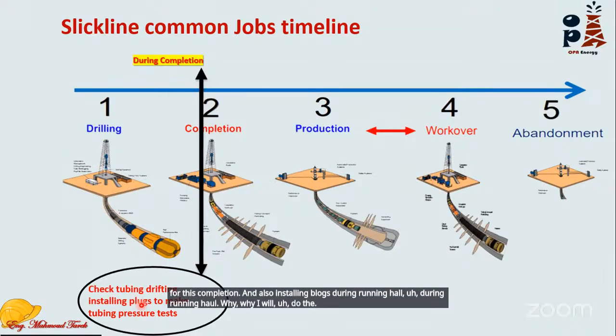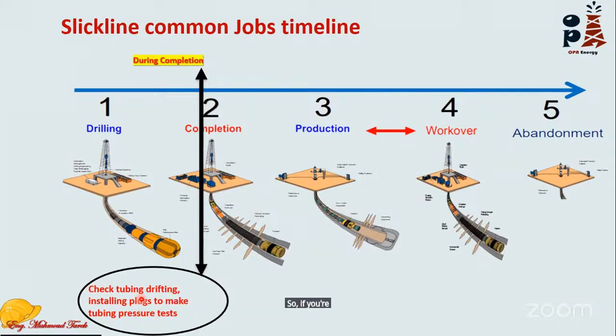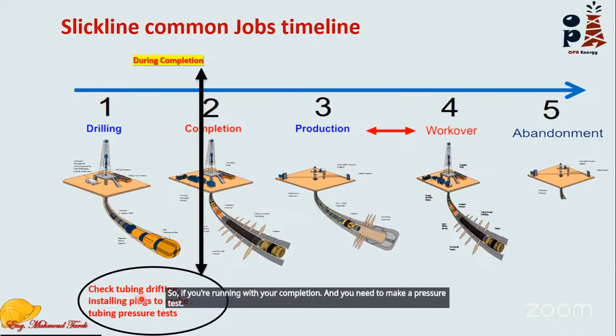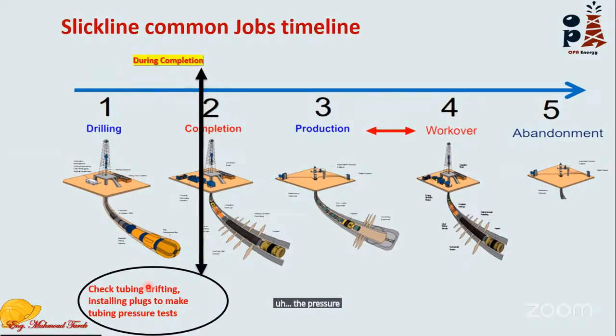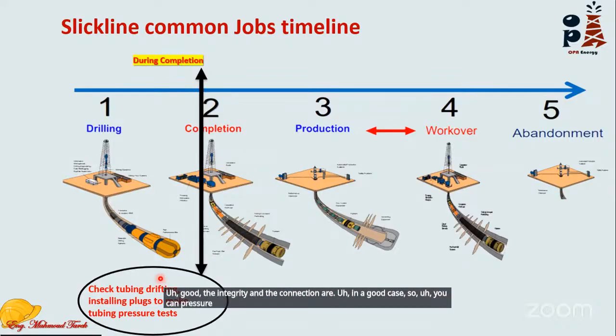Why will I do that? If you're running with your completion and you need to make a pressure test to ensure the integrity and that the connections of the completion introduced to the well are good, you can pressure test it by inserting a plug inside this tubing and making the pressure test.